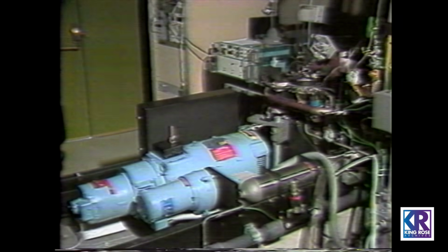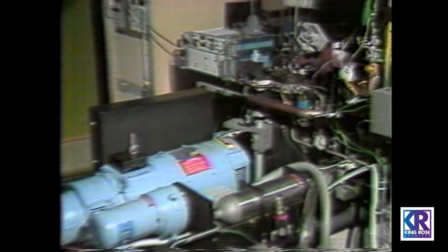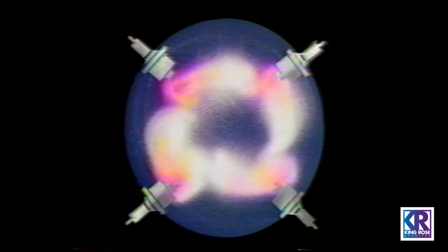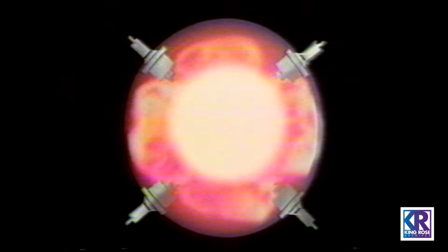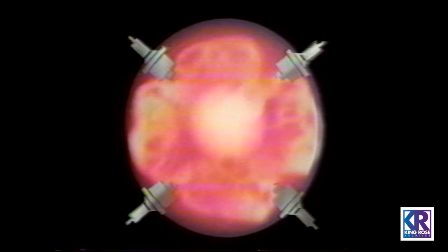To unravel the mysteries of engine knock, researchers are using what amounts to a specially designed lawnmower engine. Instead of 1, 4 spark plugs are fired simultaneously. A normal burn begins at 4 locations. Initially, the flames move away from each spark plug in a swirling pattern toward the center of the chamber. However, as temperature and pressure increase, the end gas suddenly auto-ignites, creating that unwanted ping, or engine knock.